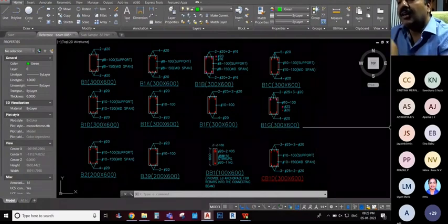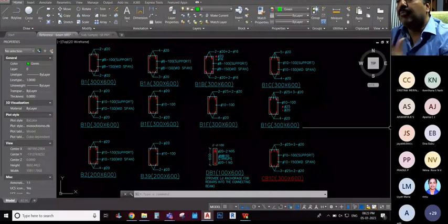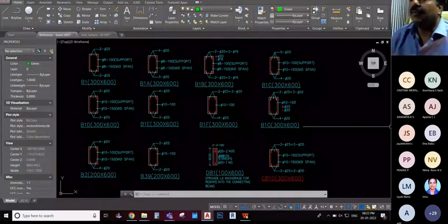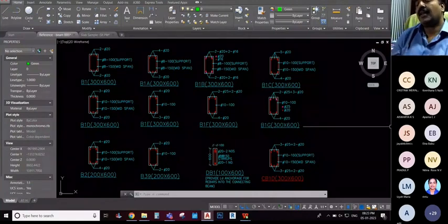Like that, you cannot splice a bar on the top side where it is support. At the support, because the working moment is at the top, you should not splice the bar. So such details will be missing in this. So without a longitudinal beam section, you should not give it like this.